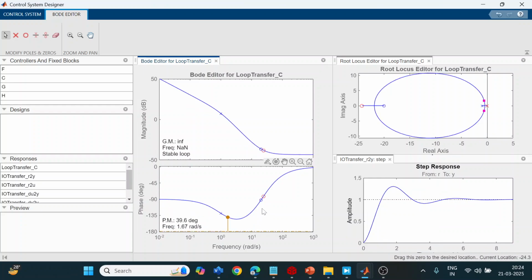If I just tell you like that, you will not understand anything. You have to take a particular problem and try to design a PI controller or PID controller. This is called the dynamical modeling of the system, or small signal modeling of the system. For the transient response analysis, we are just using this method to get the KP, KI tuning.